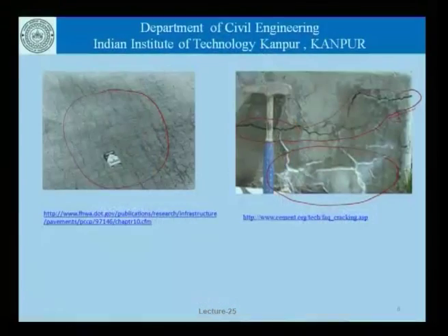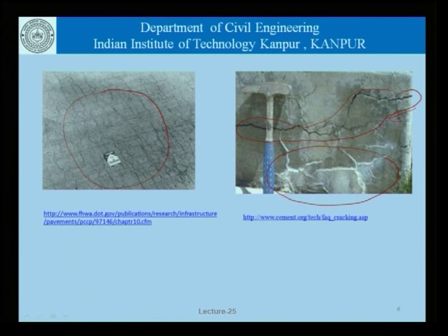So, the gel that is formed, that absorbs water and gives rise to cracks, that gel moves around obviously in the cracks and fissures that are formed within the concrete, and this is a manifestation where we see that gel exuding to the surface of the structure.